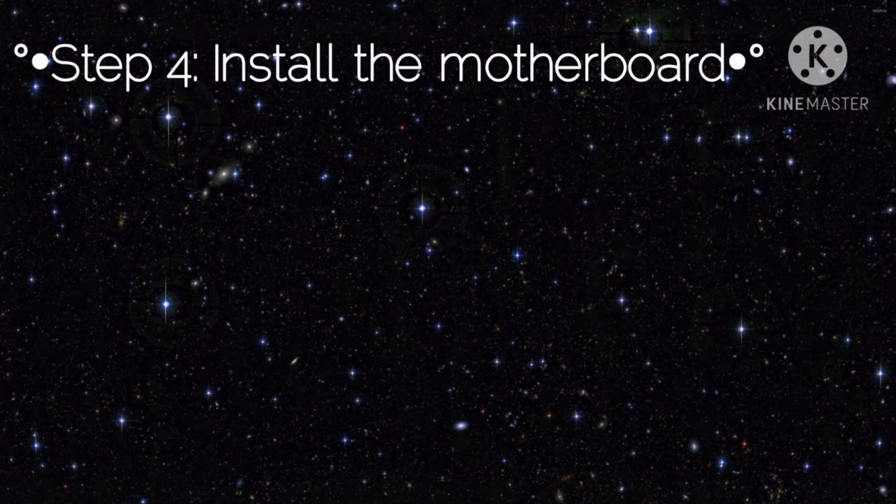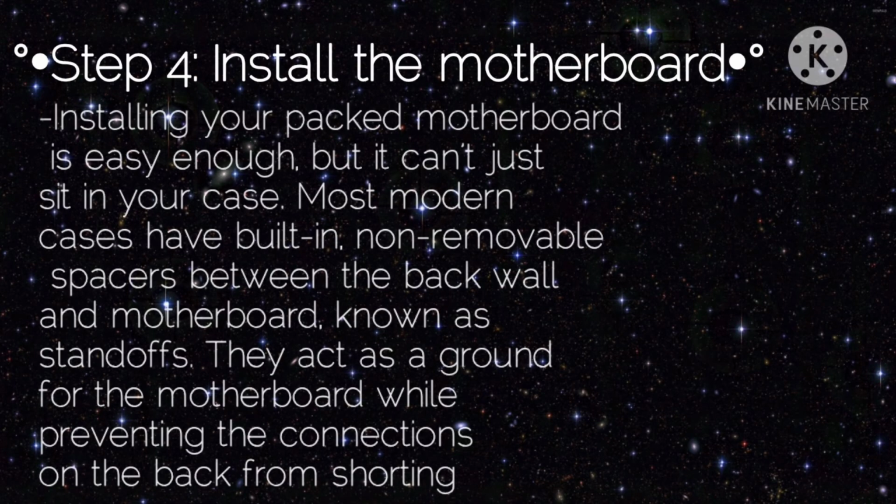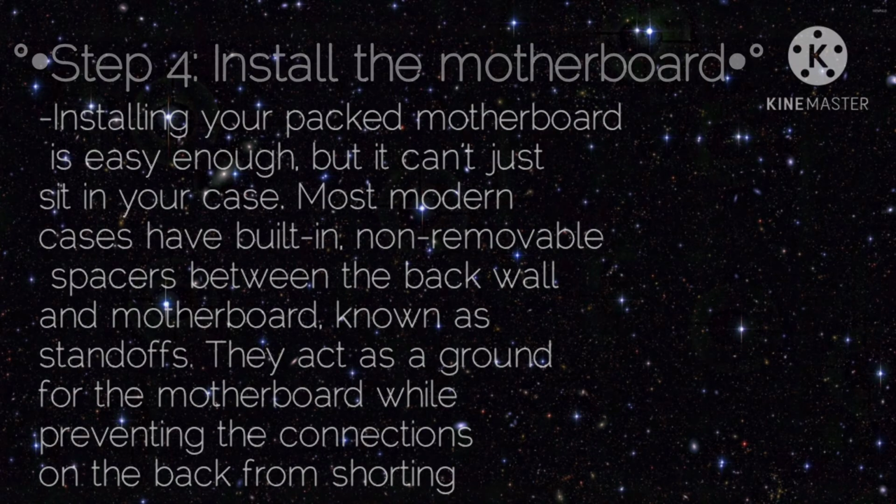Step 4. Install the motherboard. Installing your packed motherboard is easy enough, but it can't just sit in your case. Most modern cases have built-in non-removable spacers between the back wall and the motherboard, known as standoffs. They act as a ground for the motherboard while preventing the connections on the back from shorting.